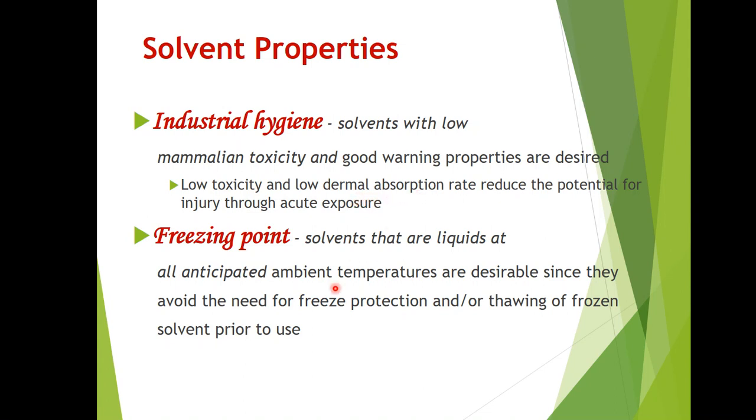So low dermal absorption. The freezing point is not a problem with us here in the Philippines because we don't have winter. But in the western part of the globe, they are considering this particular property of the solvent to freeze during cold season or during winter. So solvents should be liquids at all anticipated ambient temperatures, meaning even at low temperatures, it's expected that the solvent you are using should have a low freezing point.